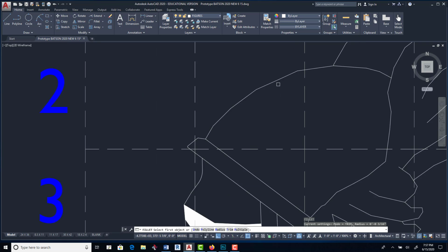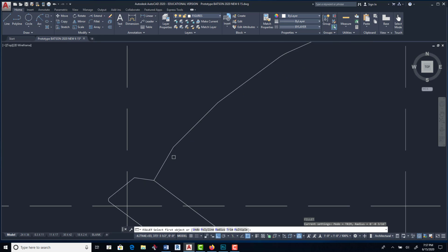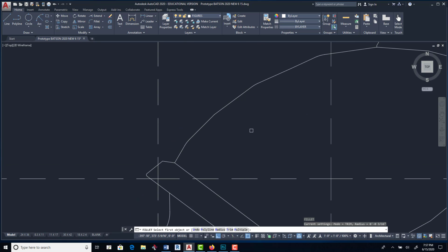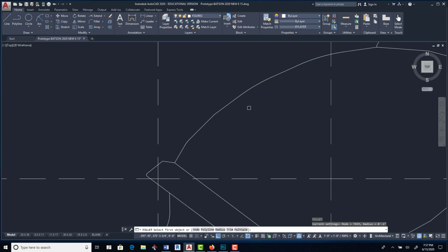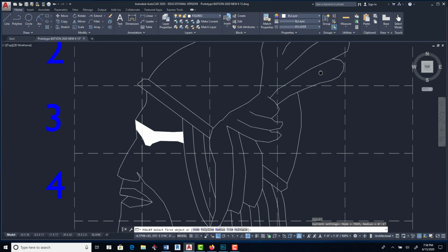So that's probably, let's try it on these. Left select, watch that curve, nice, look at that. Left select, and let's look at these two curves. Left select, left select. Let's try a bigger curve. Radius, enter, let's type in 1, enter. See what it does to that bump there. Left select, it straightens it out. Left select, it straightens them out. See now that radius, wow, the 1 will straighten out all of them. Look at that. They're all curving. There you go. So if you want to curve off all these lines, you do a radius and curve these lines up.